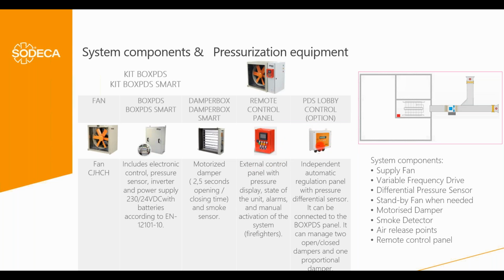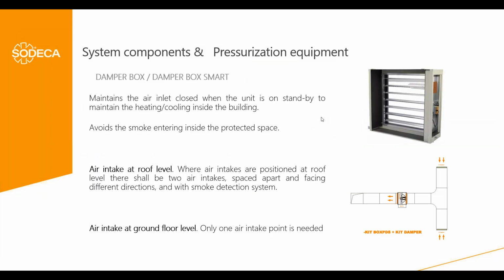We also have the possibility to include in the system these PDS lobby controls to control the overpressure on each lobby, or to control the operation of both the motorized supply damper and the motorized air release. The damper box, or damper box smart, is typically closed while the system is not operating to avoid air into the staircase, and when the system is activated, the dampers open.